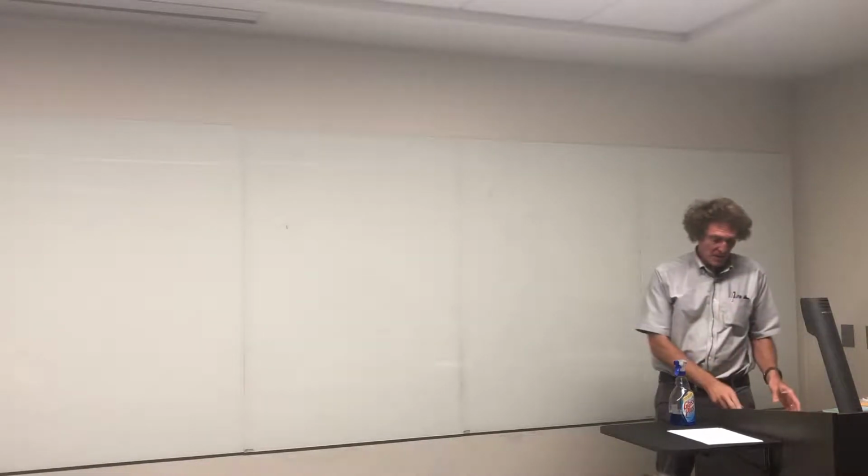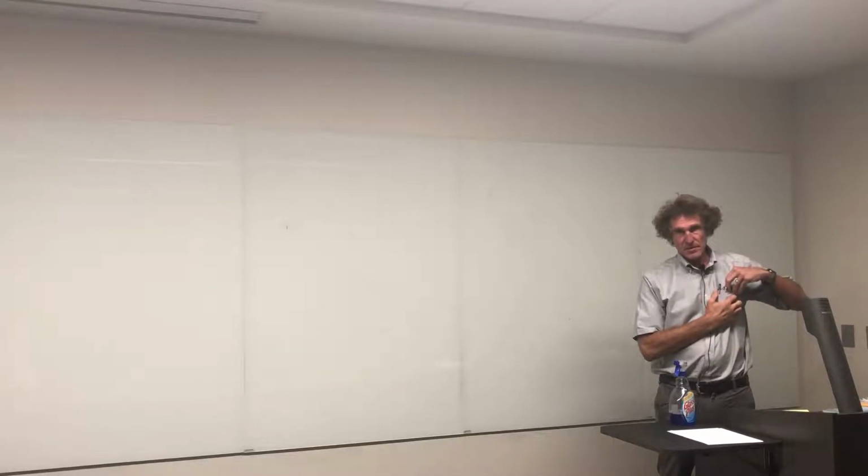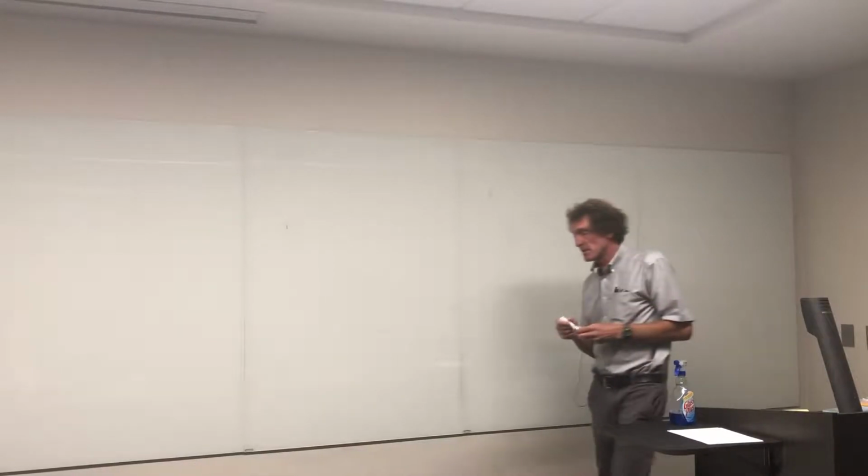All right. I wanted to cover one thing today before we go through the review of the test. And that is really going to be, well, if I can, two. First, any homework questions you have? Anything at all? For beam width, it's pretty straightforward, right? You have an equation, you set it equal to 1/2 of the maximum value of that equation if it's a power, find out what that angle is, and it's symmetric almost always.